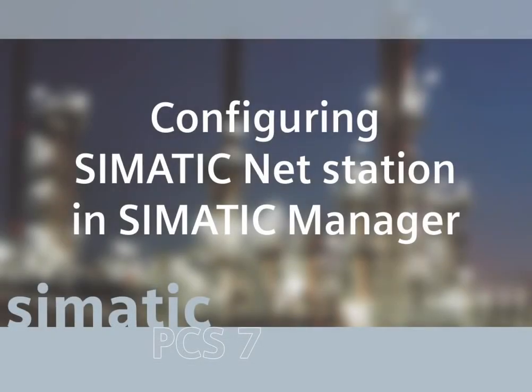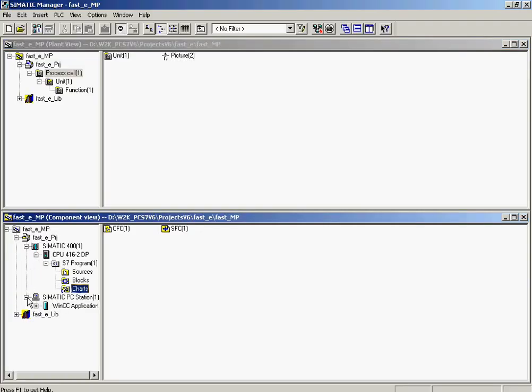along with defining the symbolic addressing of the signals for the individual input-output modules. In the new multi-project, the wizard has created a schematic station, which will now be configured in the component view. First, the name of the PC station is adapted to the name of the PC. This helps to simplify engineering in distributed automation solutions with several OS servers.